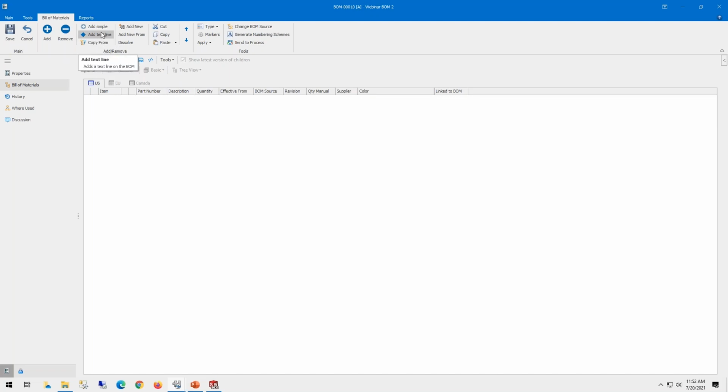an assembly. And this again speaks to purpose and what you're going to do with that bill of materials. If I want to modify the structure of it, like it's a multi-level assembly with sub-assemblies and sub-assemblies, and I want to be able to dissolve those and change the way they are, then I'm going to use the copy from option and just take a snapshot of that architecture and then tear it apart.